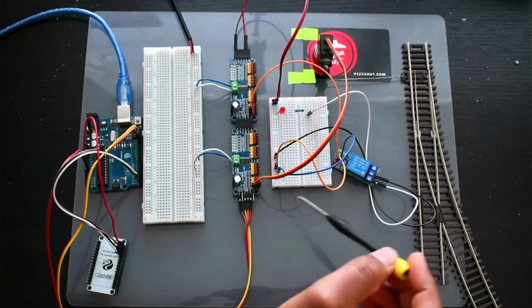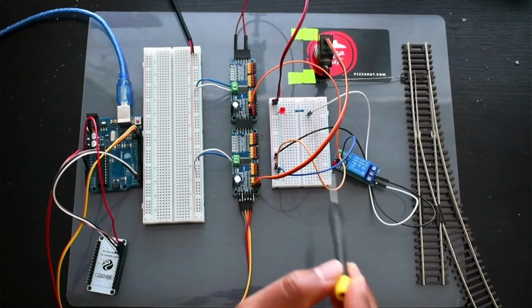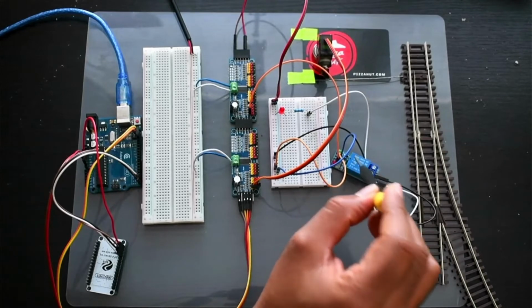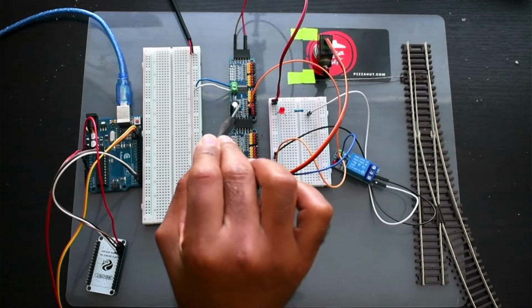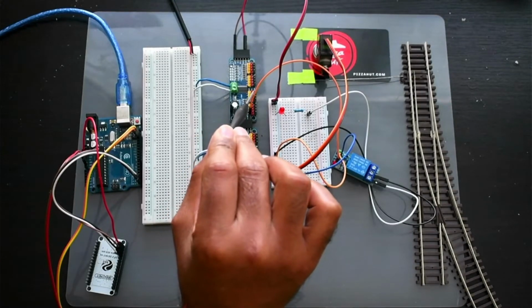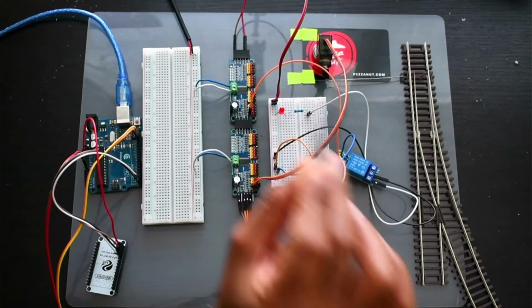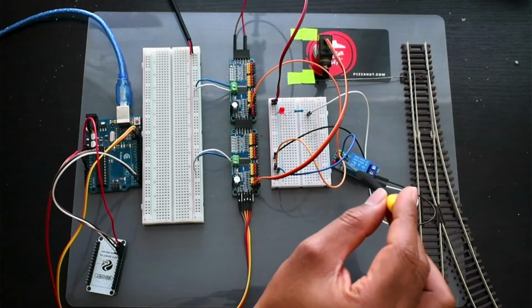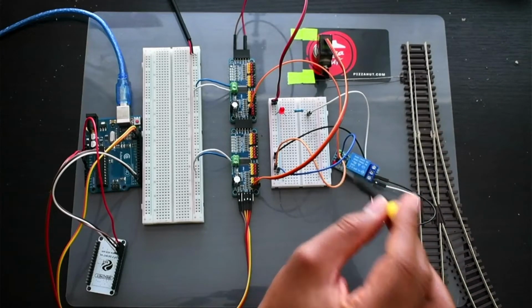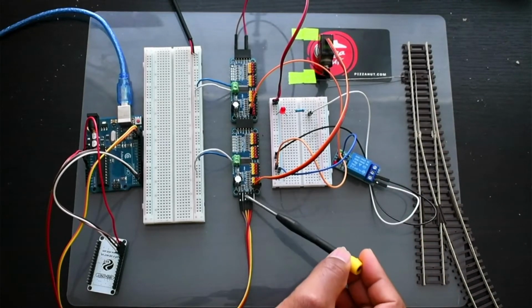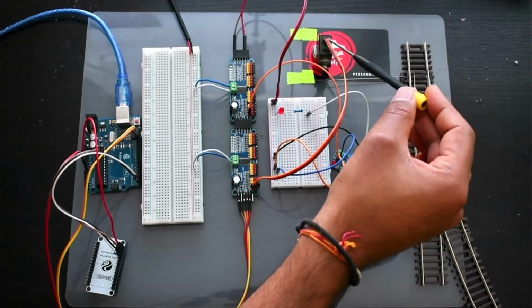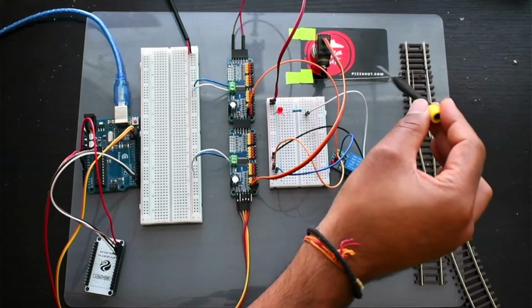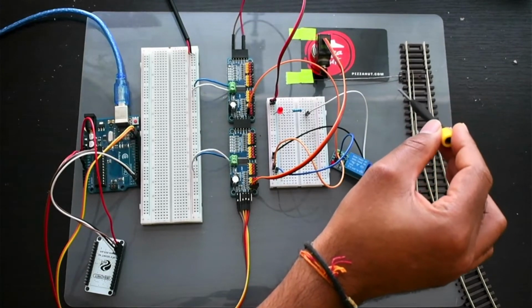In this breadboard you can see there is a blue and orange wire which is going to this relay switch, to power up this relay switch. And from the second board, pin number 0, the orange wire is coming to the relay switch to control the on and off position of the relay switch. And here you can see from board number 0, pin number 0, there's a servo connection going to the servo, which is to control the throw and close position of the servo.